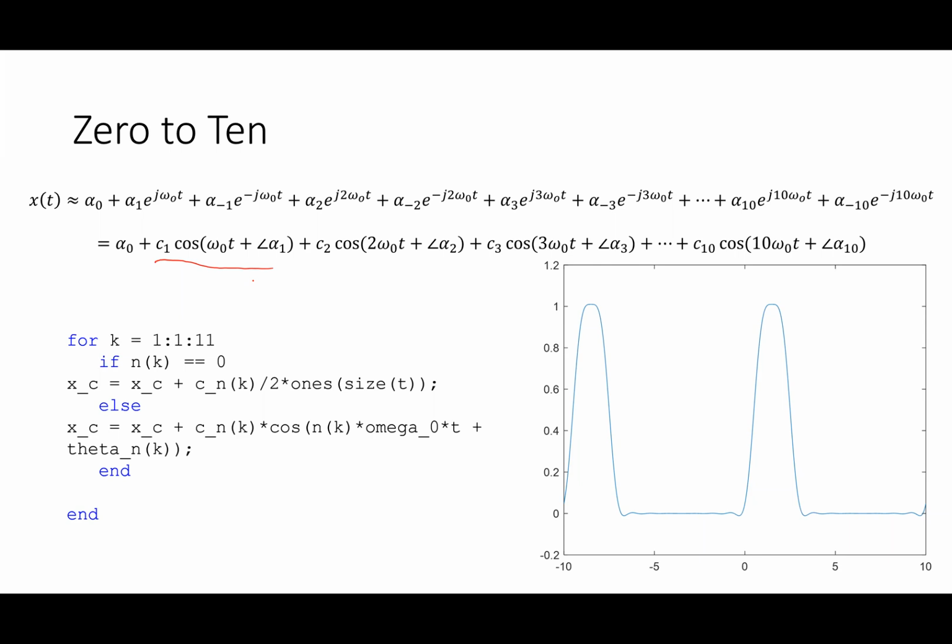I want to make sure that the individual steps in my time vector are small enough that I can accurately represent the waveform. And by the time I'm at a signal that has 100 times the fundamental frequency, it has 1/100th of the period. So I made sure my time step was 100 times smaller than the smallest period I had.